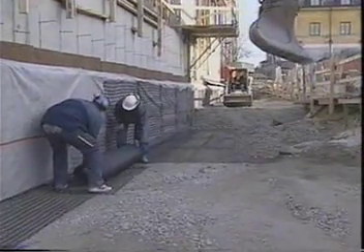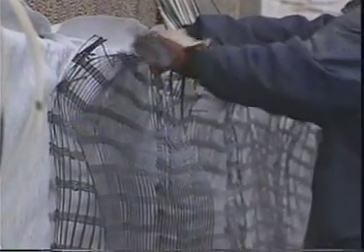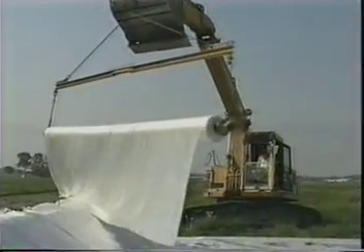Finer polyester geogrids are produced by forming a skeleton of orthogonal arrays of multifilaments or low-twist yarn with knitted or interwoven junctions. These grids have a protective coating of PVC, polyolefin, or other materials, and are suitable for the construction of vertical walls or steep slopes. Polyester multifilaments may also be converted into a low-twist yarn, which is then woven conventionally to form a high-strength geotextile sheet. This type of fabric is employed for the basal reinforcement of an embankment constructed over soft ground.